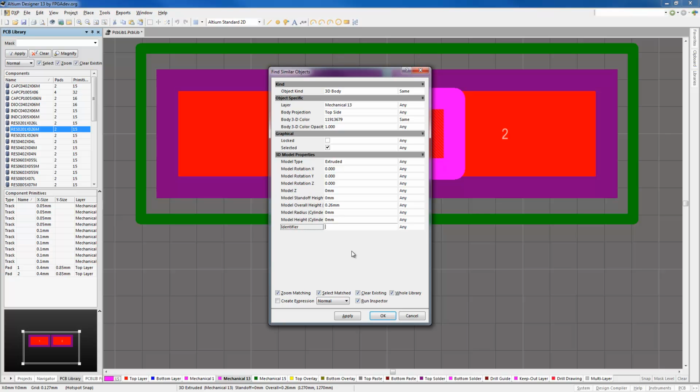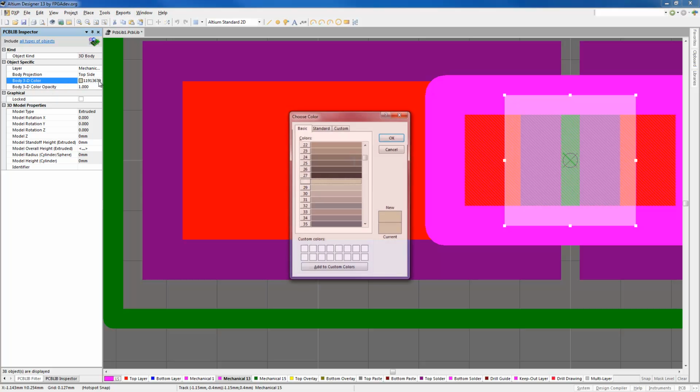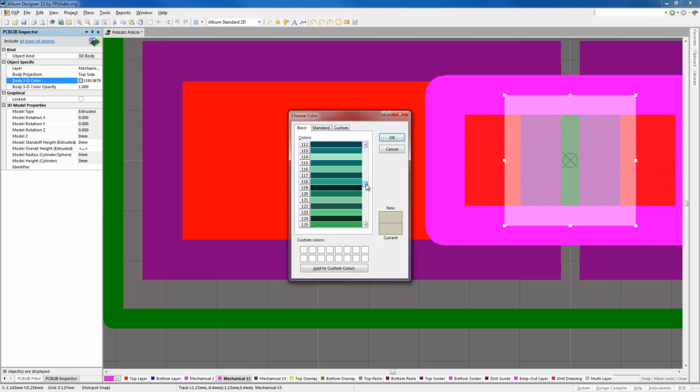All right. So I'm going to press OK. Okay, and you're going to notice that there are 38 objects selected, because effectively we've had 38 different components over here. And what I can do over here, for example, is 3D color. So I can click on this and I can change all the properties at once. In fact, what you're seeing over here is all the properties of all of the 3D bodies. If there's something that's different on those properties, they'll put the little caret heads over here with the 3 dots, saying, look, each one of these has a property that might be different from each other. But these are all the same, so I'm going to click on this little button here and change its color to black, for example.